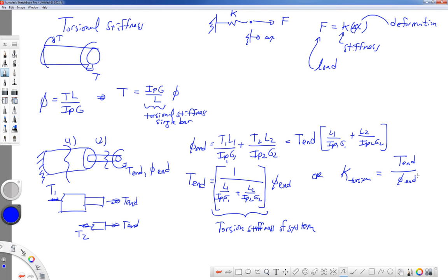When I worked at General Motors, we would test the front end of a structure for its stiffness, in tension and in torsion. And if we did any structural modifications to it, we could either numerically or in the lab test to see what the new stiffness was, to see if we were headed in the right direction. If we wanted to make a stiffer front end structure, then we would increase the sizes of the cross-section members, cross members and so forth, and then we can tell whether or not our design was having the effect that we wanted it to. All right, so that'll wrap up this lecture on stress state from torsion and torsion of assemblies.